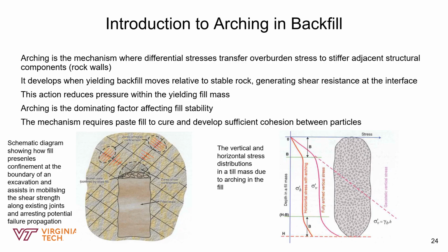And so as the backfill yields, it settles and moves relative to the stable rock wall. And this movement generates shear resistance at the interface between the rock and the backfill. And so this interaction is very crucial because it effectively reduces the pressure within the fill mass itself, meaning the fill doesn't have to support its own full weight.